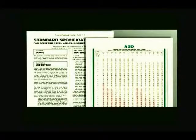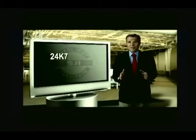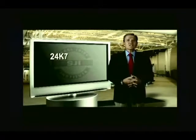It will be 24 inches deep and will comply with all of the other requirements of the specifications and the load tables. Additional standards regarding bridging, end anchorage, the allowable deflection, camber, paint, among other items, are also listed as standards in the specifications. These standards must be adhered to in order for a joist to carry a Steel Joist Institute designation.